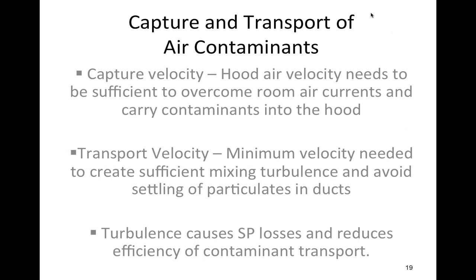Let's say that area 2 is 4 square feet. What's velocity 2 going to be equal to? A1 was 100 feet per minute, 1 square foot. A2 is 4 square feet. What's V2 going to be? Is it going to slow down or speed up? It's going to slow down, right? And the area is 4 times as much as what we started with. So it was 100 feet per minute, so it's going to be 25 feet per minute, right?